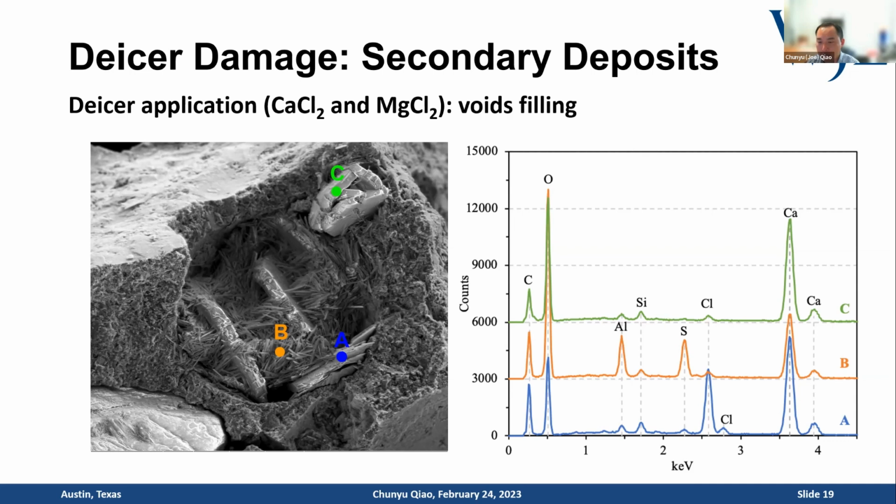So when I talk about the process here, I'm not really talking about air voids. I'm more talking about the matrix pores, gel pores, cavity pores, those things between the hydration products. So yes, if you have chemical admixtures, that will very commonly change the air entrainment or air entrapment, right? So those air voids are not really the pores I'm talking about in those slides. Those slides are more about the gel pores or cavity pores in the matrix.